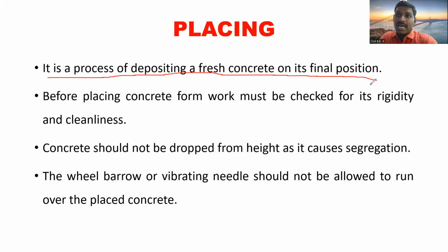In those components, we have to deposit the concrete in its final location. That is the placing. Before the placing of concrete, the formwork must be checked for rigidity and cleanliness.